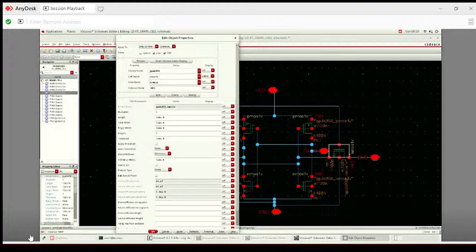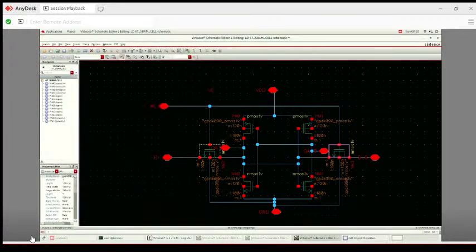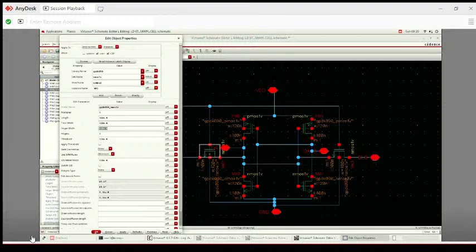So let's write it. So 120 nanometer width, we have, sorry, 180, it will be 180 nanometer for this access transistor. Let's press it, remove the 2 and write 8. So this way we have settled 180 nanometer width for this access transistor, and in a similar manner we will set it for the other access transistor. It will also be 180 nanometer. Okay, so access transistor sizing is done.